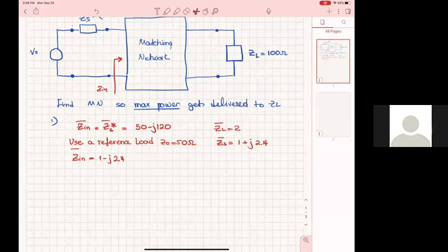I would probably use either an open circuited stub or short circuited stub, depending on how we're realizing the circuit. Before we go to the design, how you specifically materialize it, what kind of tool are you going to use to get there? That's what I'm asking. We'd go about finding the reflection coefficient and then VSWR. No, tool. Are you going to use MATLAB? Are you going to use something else? Are you going to use the Smith chart? Are you going to use analytic models? What are you going to use? What does each one of you use when you try to solve these kinds of problems?